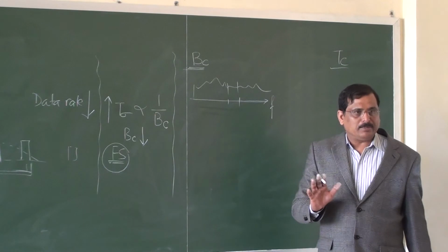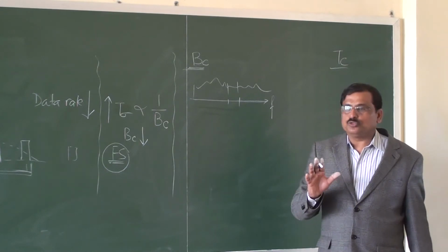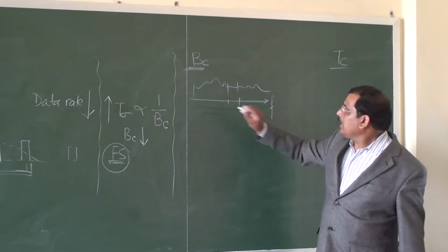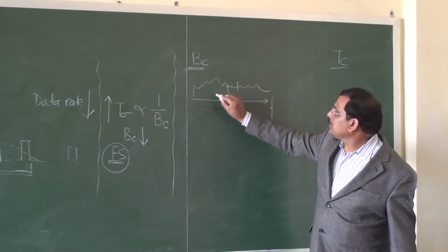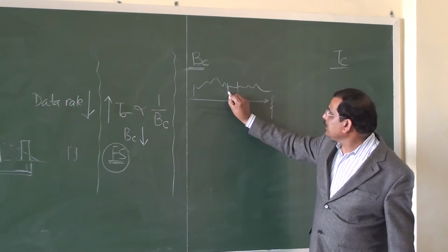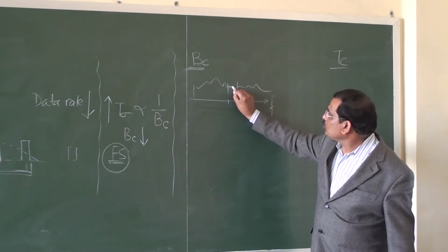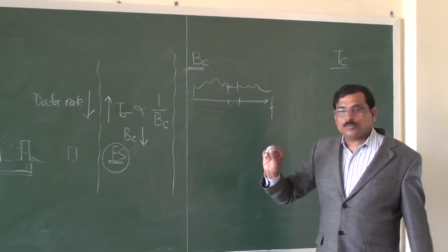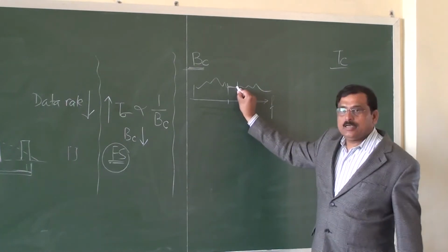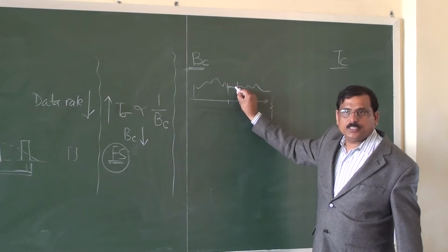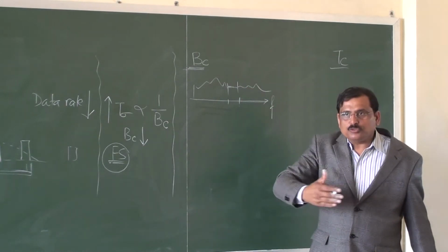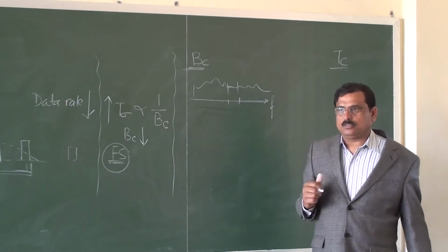The channel is not going to vary much. The channel is going to show you almost the same amount of gain. Here the gain is this much, here the gain is this much, here the gain is this much, but over this period you find the channel is going to show you almost the same amount of gain. Because the phase has to change, but the phase is changing linearly. There is no non-linear phase change. Phase is also going to change gradually as the distance is increasing.